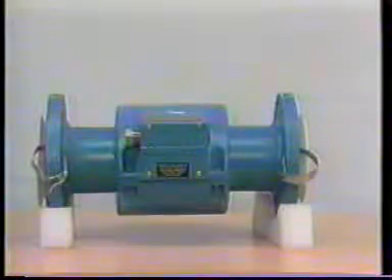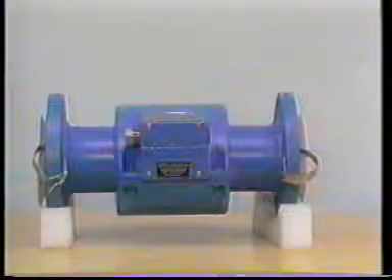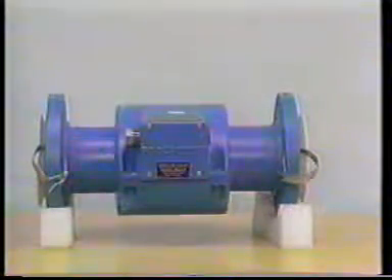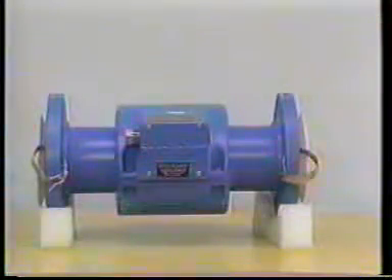The voltage induced in the fluid as it passes through the magnetic field is picked up by the electrodes and measured. This measuring device can be calibrated to indicate flow rate, volumetric flow rate, or mass flow rate. Two general problems must be dealt with in the application of these devices to flow measurement. One is signal distortion and interference caused by extraneous voltages that are either induced or already present in the system. The other problem is coating of the pickup electrodes by a non-conducting material.